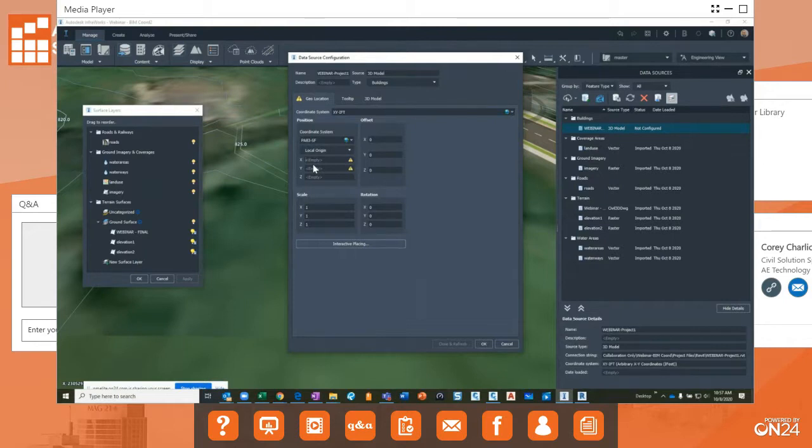So our X is going to be 2305,241.84 feet. Our Y is going to be 195696.34. Have an elevation here. Our site is at 825 for an elevation. And we need to rotate our Revit model from project north to true north.